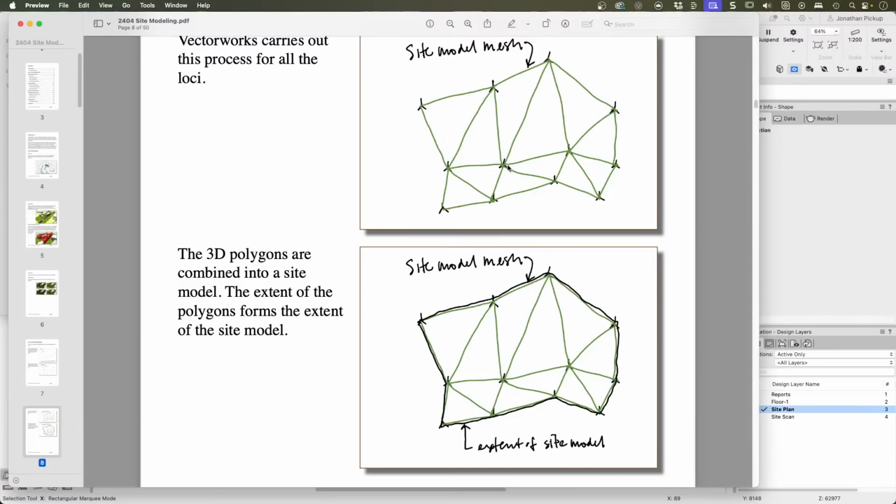If that was 10 feet and that was 30 feet, then halfway along it is going to be 20 feet, and that's where 15 feet is. So you'll end up with a contour that goes from there to there and then comes to here. Sometimes you end up with very funny shaped contours, and it's really a result of how Vectorworks works through the mathematics of all these objects.